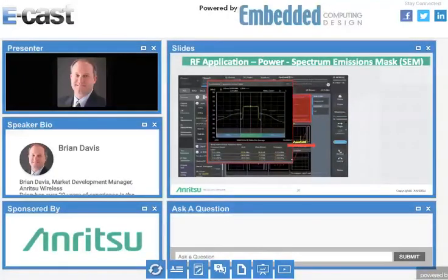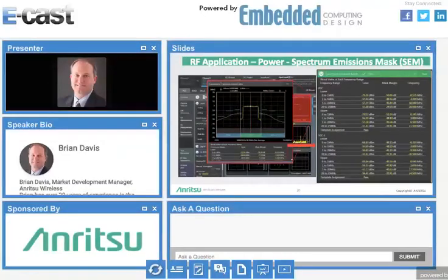Spectrum emission mask, this is important when you're looking at 3GPP type testing. Everybody always wants to be aware if you're below the spectrum mask, you're not radiating power outside of where you should be. But the power at the frequency offset point from the center and the frequency of the RF signal output from the UE is measured. You get uplink carrier aggregation from the primary component carrier, the supplementary carrier. They can be selected and queried too. They're over on the right. And then if you even have a third uplink too, that can be queried as well.